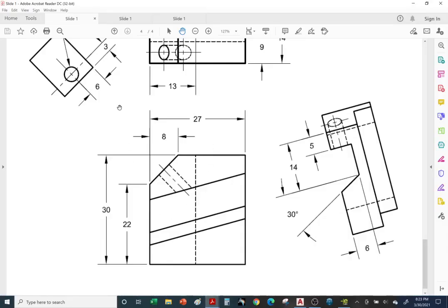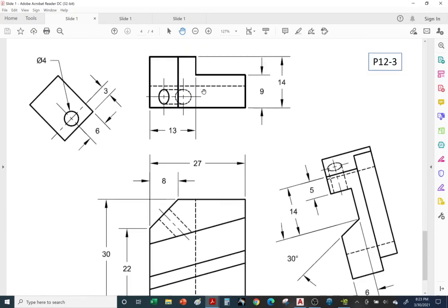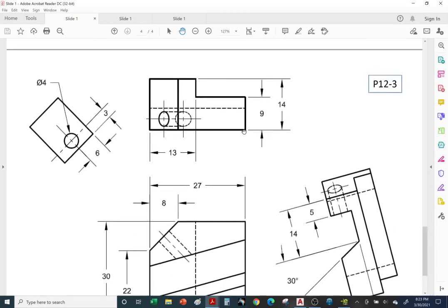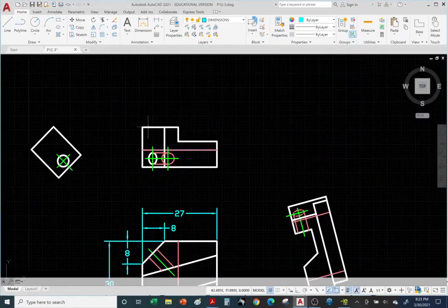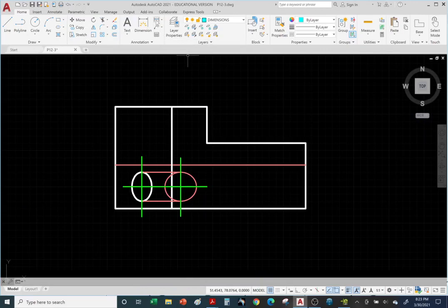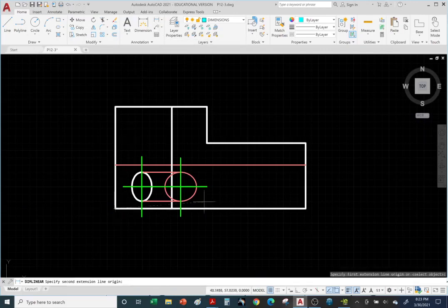Okay, so we took care of the front. Okay, let's take care of the top view. Okay, so we're going to go from this front datum. There's more surface area than the back. So we'll dimension front to back, and then we'll dimension this thickness here, right, of 13. Okay, let's take care of the 13 first. All right, so go to the top view. Okay, so we have the dimension of 13 from this vertex to this one. That'll give us that thickness here.